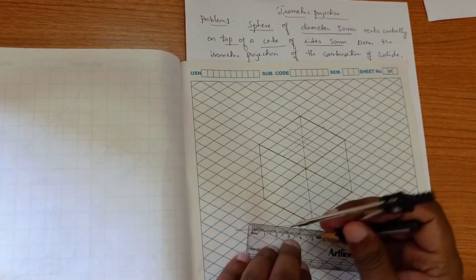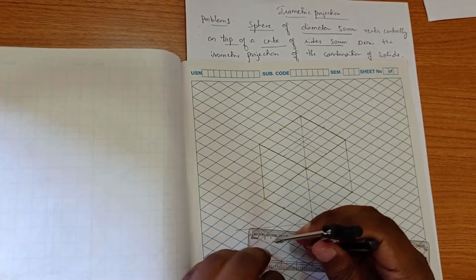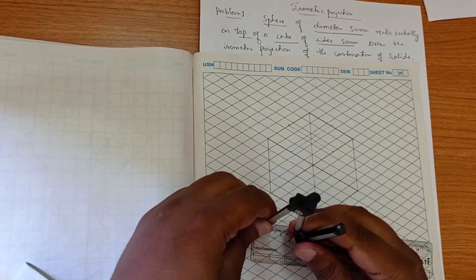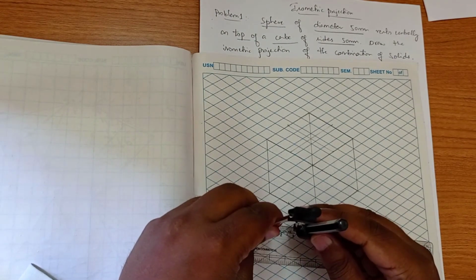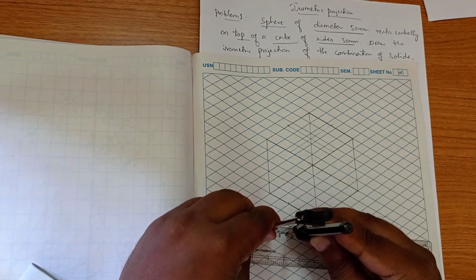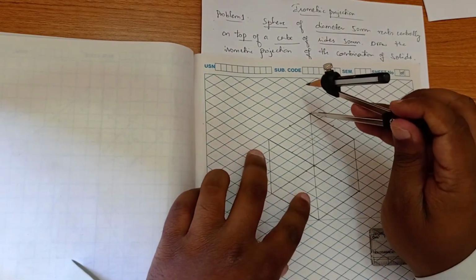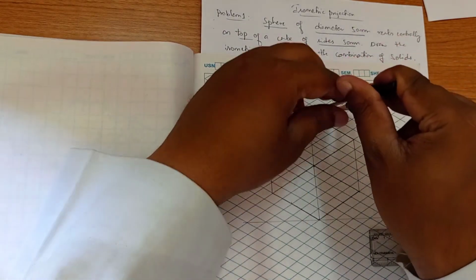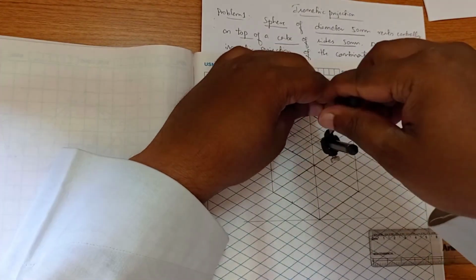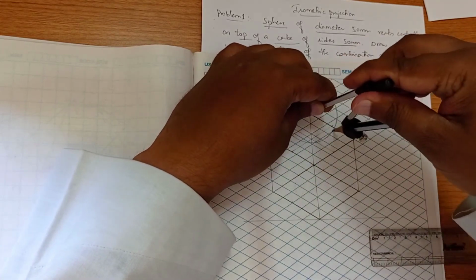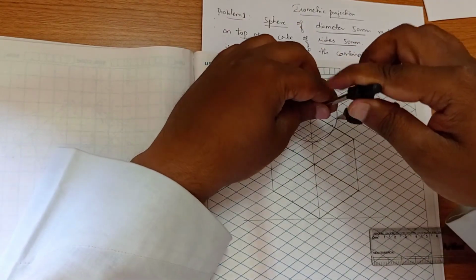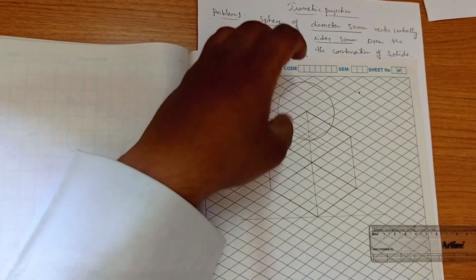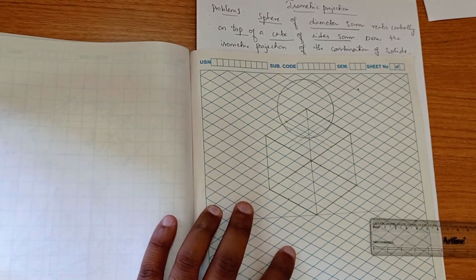Sphere is the only solid which will be drawn with the actual scale. Except a sphere, all the solids will be drawn with the isoscale. Remember it. Always remember it, because if we incline a sphere at whatever angle, 30 degree, 40 degree or 50 degree, you will get the same circular shape only. There is no change in the shape in case of your sphere.